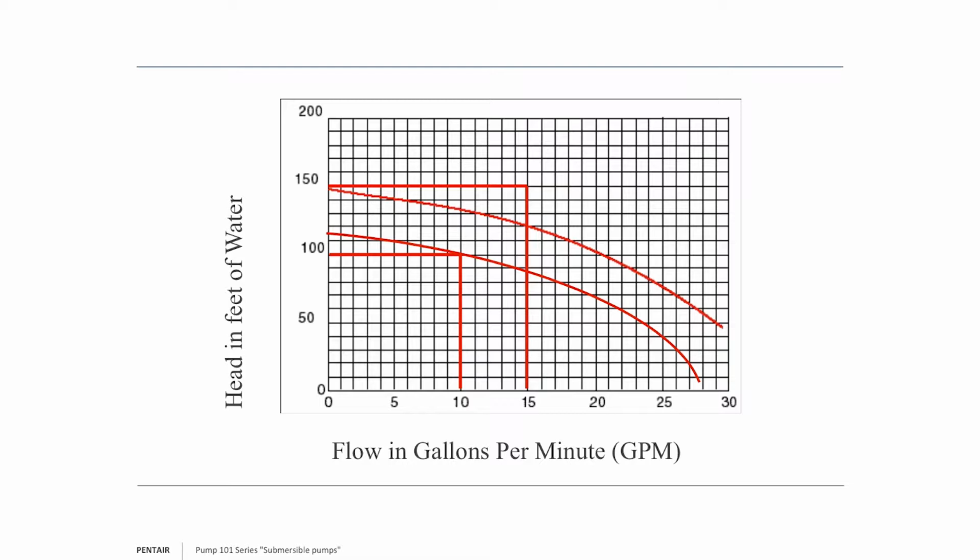Now, I also point this out because, especially with centrifugals and larger units, we inadvertently trim the impellers all the time. It's called cavitation. Cavitation damage erodes not necessarily your flow, but attacks directly your ability to build pressure and head. So often we trim the impellers nowadays accidentally.